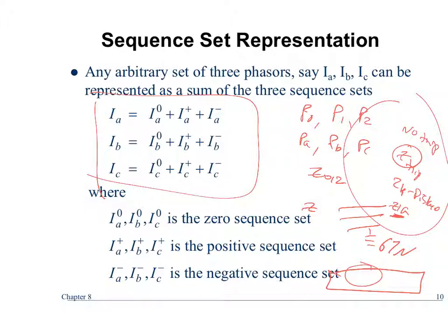Just based on the impedance you picked. It can't be just current, because it's voltage dependent as well. So it actually needs to know those characteristics to be able to determine that, and you have to set all of those, plus the delays associated with it. Do you reclose? Do you not reclose instantaneously? I can get into all kinds of things, but I will bore you.